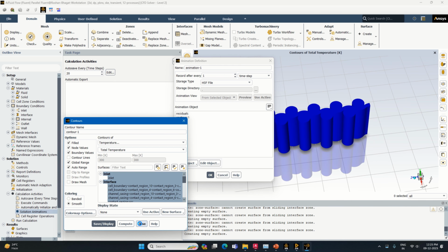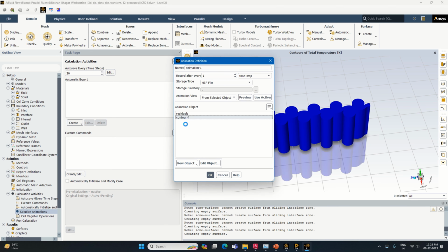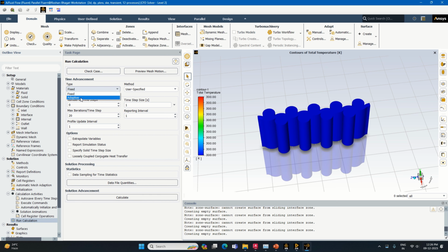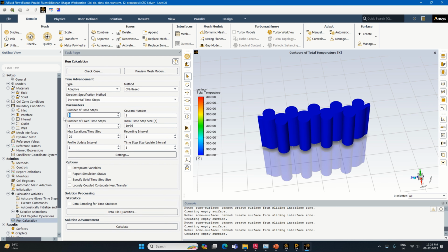display, then close this, click on the contour and make it okay. So this is a float scale, otherwise you might see the exponential scale also. It depends, whatever you want, accordingly you can put it here. So adaptive I will put around 200 here, or let's take 100 first for our sample calculations, make it 0.5, and let's start calculating.